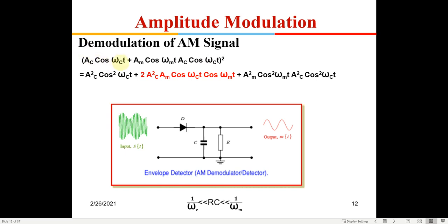Now I am sending it from the transmitter side itself, so I am just squaring it. a plus b square is a square plus 2ab plus b square, so in that 2ab factor this cos omega ct gets multiplied with that cos omega ct. That is done within itself without the requirement, so the signal being transmitted is used to multiply here and get back my baseband signal. So now you have a baseband signal.